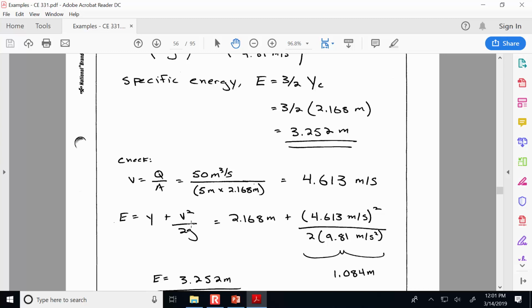And just at the precipice of starting to choke the flow, like when you've just barely put so many obstructions in the channel that it's going to begin to pool upstream, then the water will flow at the critical depth over those obstructions.